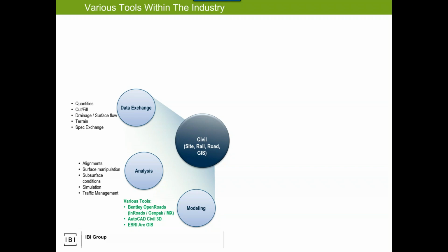The other thing to note, if I'm in the world of Bentley, everything is one file format. So I can have my building and my civil. At the end of the day, it's all the DGN file, and they talk. At least they can link to each other. If I'm in the Autodesk world, my Civil 3D is a DWG, my Revit is an RVT, and wouldn't you know, I cannot reference my building into my civil. So you've got to jump through hoops. Not challenging hoops, but you need a workflow.